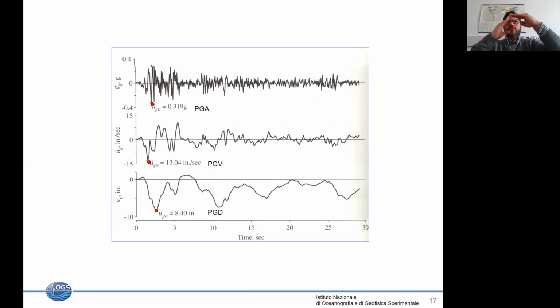Okay, so now it means that I go from something which is dominated by low frequency, and you see it in the displacement, to something that starts to be dominated by intermediate frequencies, right? My peak now is close to the corner frequency, where I have a maximum. Do you agree? And what happens now if I go from velocity to acceleration? I have to multiply again by i omega, right? Yeah. So the low frequency will be even diminished, and the high frequency will become predominant.